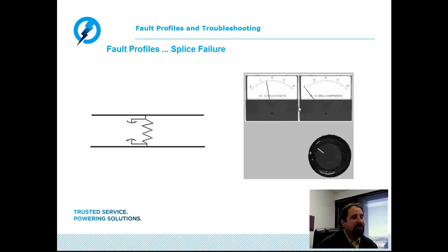We may also find that the cable fault may not break over on every cycle of the surge generator. Again, that is a good indication that the gap is very large, that we need to actually build or stack voltage on the circuit until we reach a point that we're able to break down the excessive gap. So a splice failure can be rather difficult and could require a lot of energy and voltage in order to successfully get it to break down.